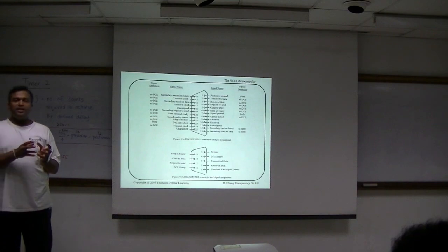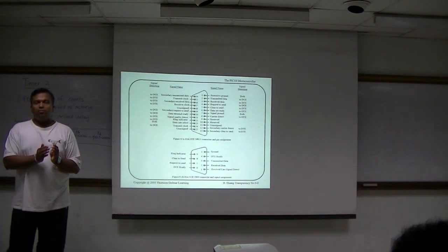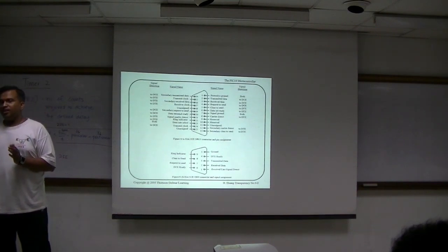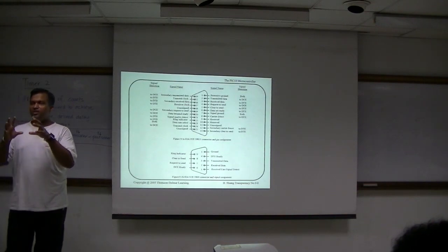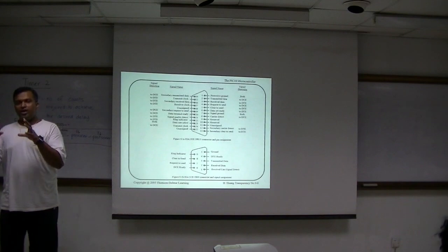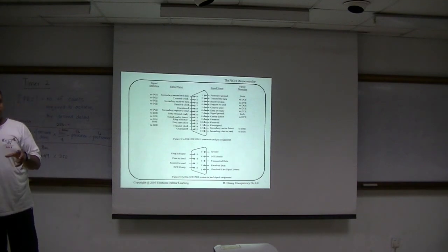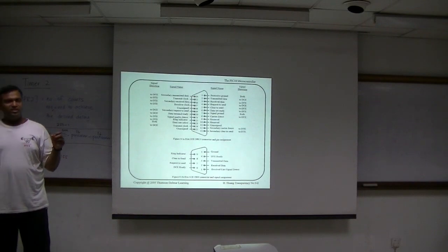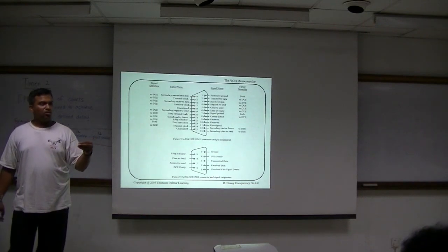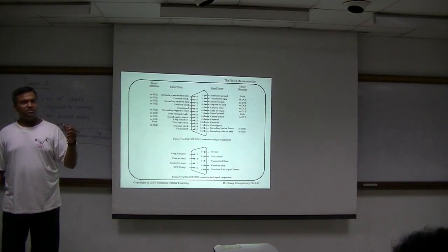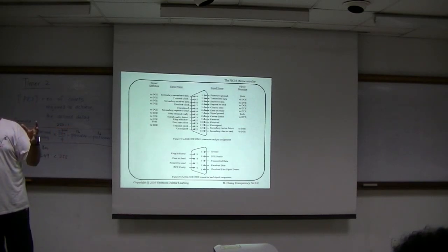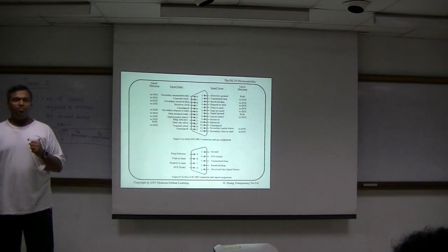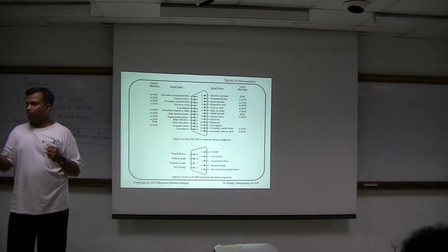But let's say you want to send data from a microcontroller to your computer. Suddenly you want to do some data analysis. You develop a GUI, graphical user interface, using VB, and then you want to capture the data from the sensor. The sensor is connected to the microcontroller, and each time it captures, let's say you write an interrupt program, every 1 second it captures the input from the sensor and sends it to the computer.